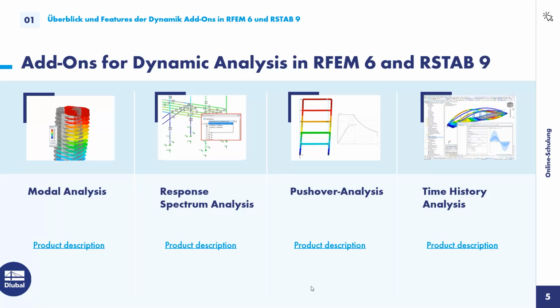And in the end, we get a force-deformation curve, the capacity curve of the structure, which itself is a great tool for engineers, since you can just simplify your complex structure to just one graph. So you can compare it just like with a single degree of freedom system by yourself. And the comparison with single degree of freedom systems is also used in this pushover analysis.